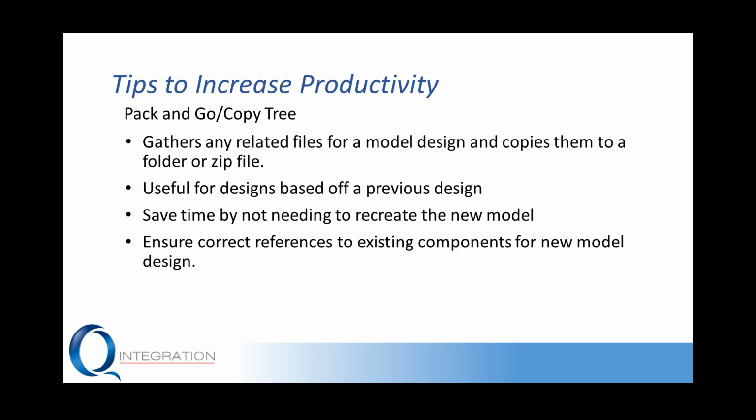So lastly here, for some tips to increase our productivity: Pack and Go, or Copy Tree if we're utilizing Enterprise PDM. What's really great about this is we can gather all the related files for that design inside that model, and we can copy those to a new folder or zip file. And it doesn't actually have to be all the files. We can pick and choose which files we want to bring over.